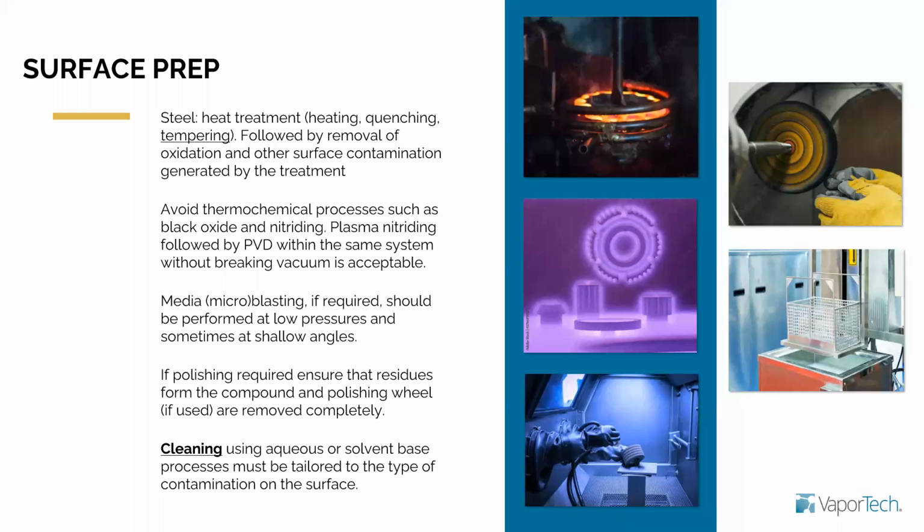These are case hardening processes in which you diffuse some elements into the material. You don't add anything to the surface, you just modify the surface of the material, and you increase the hardness locally. You're not going to get the same hardness you would have with a coating, but you improve the properties of your part. The problem with those is that they leave some residues and make the surface not ideal for deposition, either by PVD or PECVD, which are deposition processes.